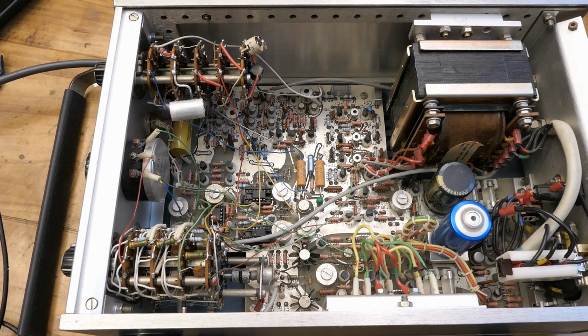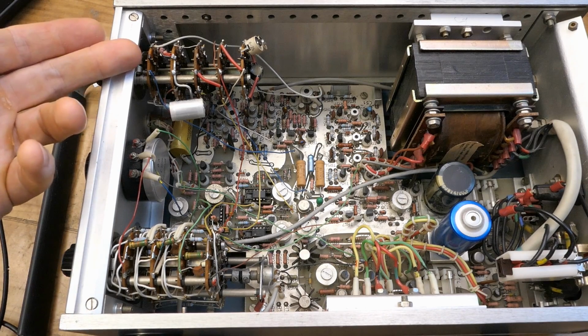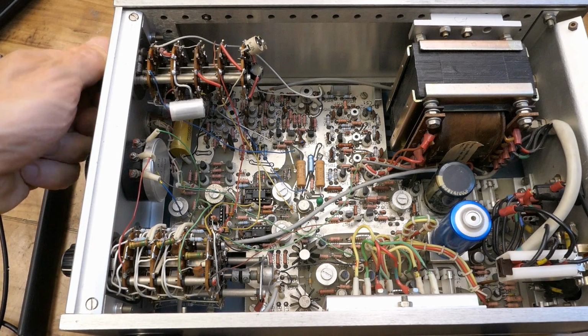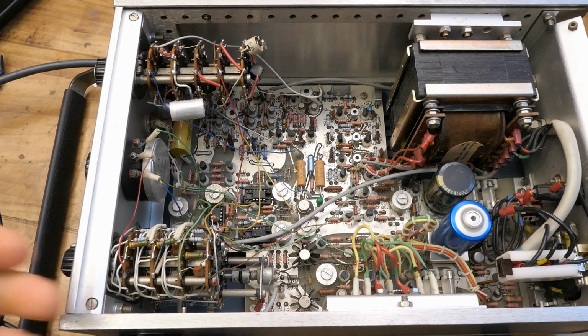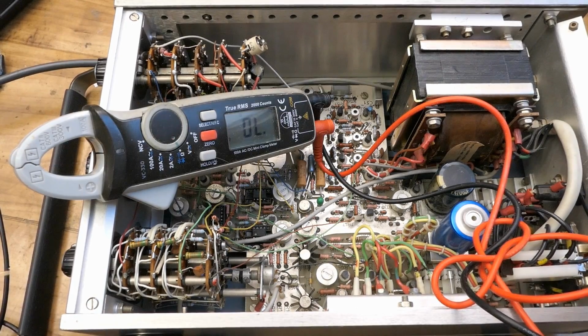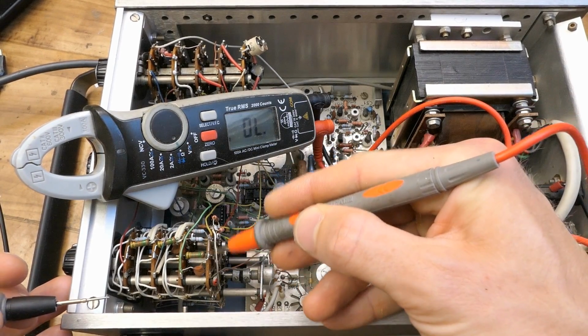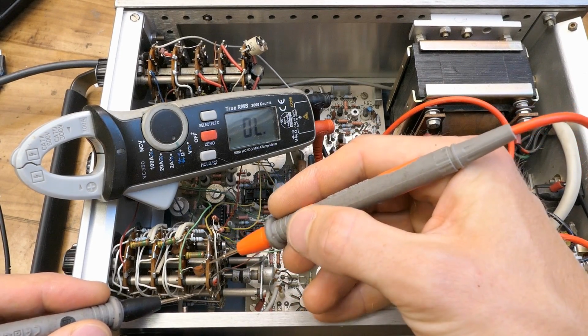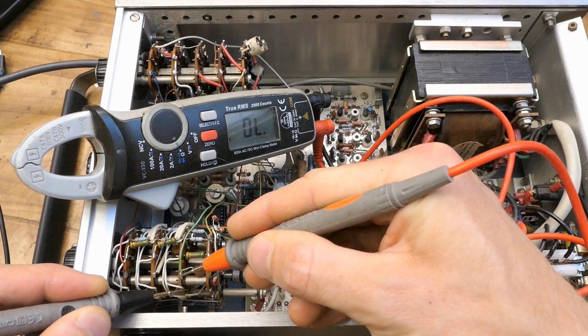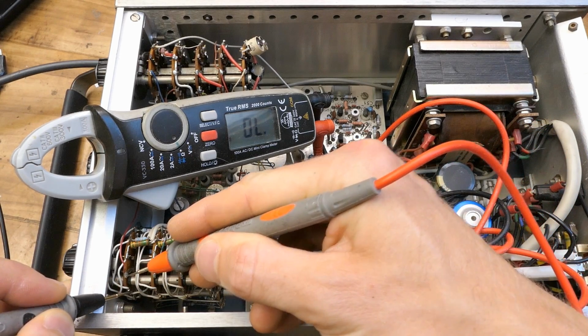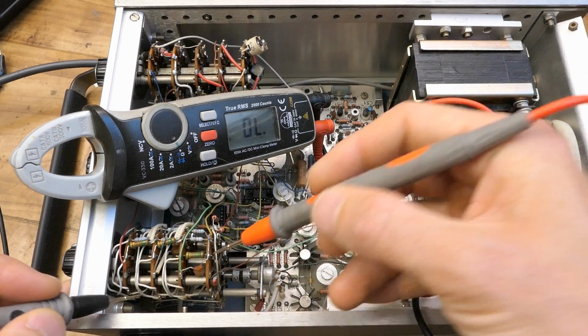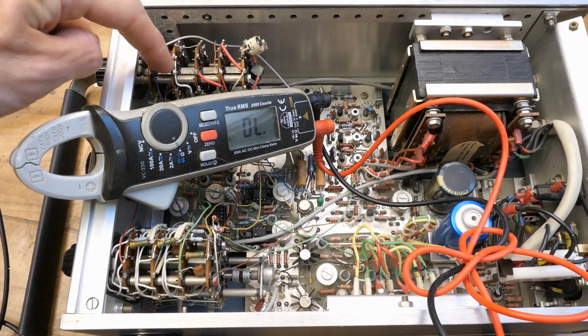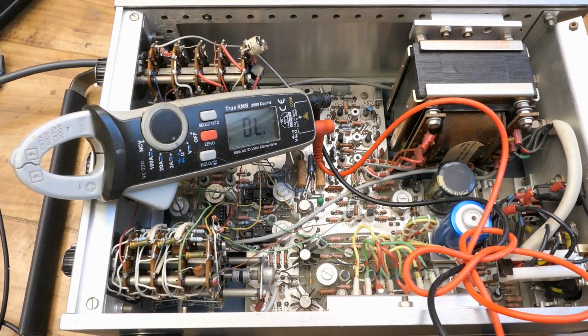Another very common problem, especially in older devices, is poor contacts in these switches, but again the problem is happening in all positions of them. Theoretically it could be one story of these multi-story switches not making contact in any position, but this makes contact in all 4 stories of it. And this 5-story rotary switch also seems to work everywhere. I measured it. Of course now it's off.